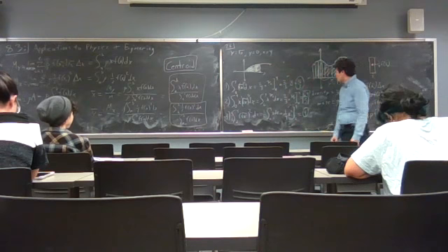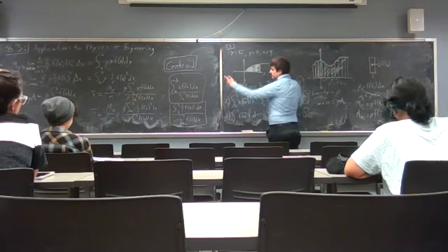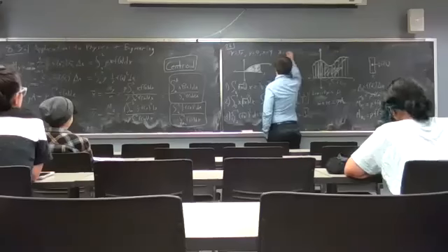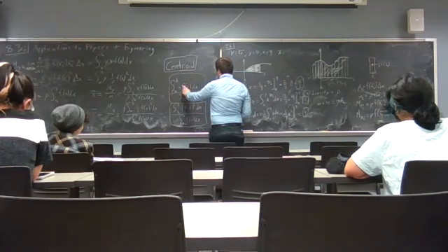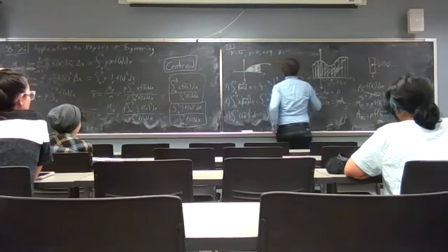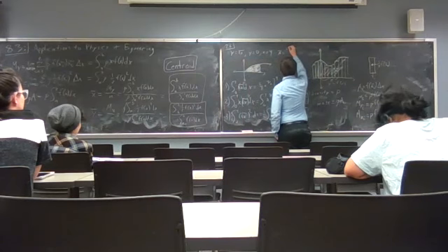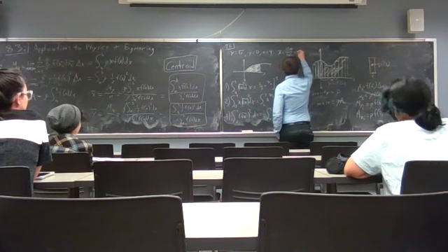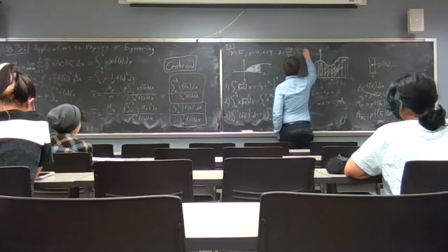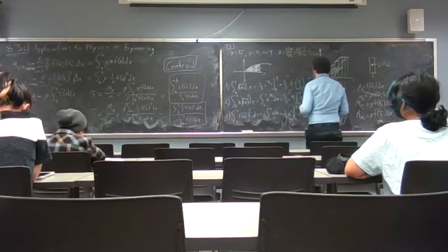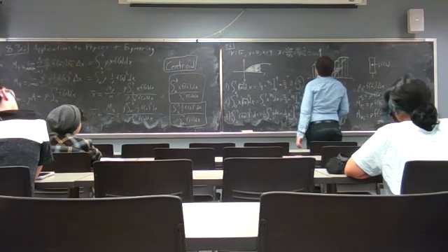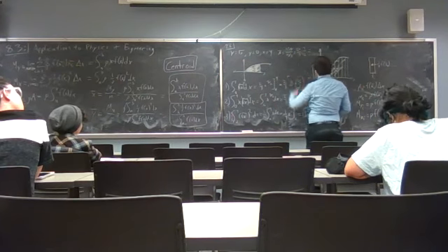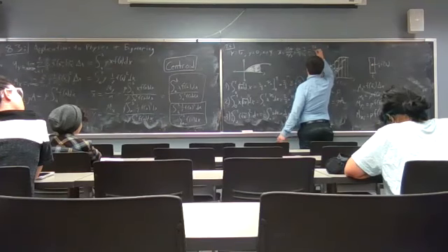Okay, good. So now we just find both our values. The centroid x bar is going to be the second one we found over the first one. So we just take 64 fifths over 16 thirds, which is 64 fifths times 3/16. 64 divided by 16, can we do that? Yeah. What's that? 4. 4 times 3 is 12. So it's 12 fifths.